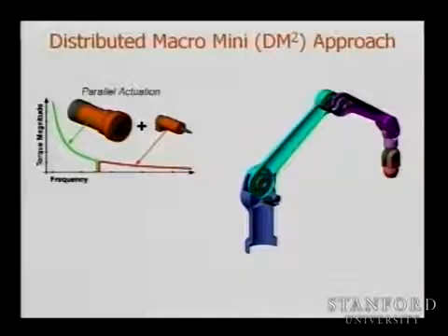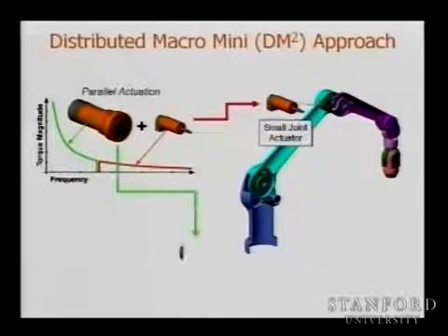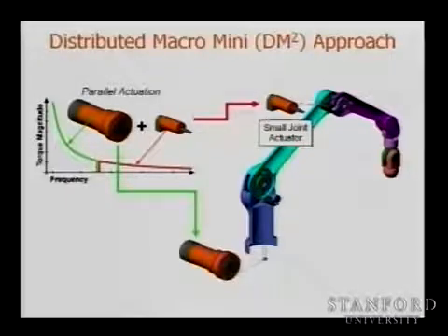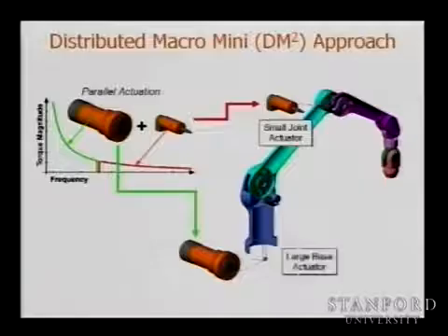We never think about it, but we can design the robot not with one motor, but with multiple motors for each joint. Like humans have multiple muscles actuating, and actually different types of muscles. So you can place a small motor, the structure will be light, very safe, and you put a big motor at the base. You remove the weight.